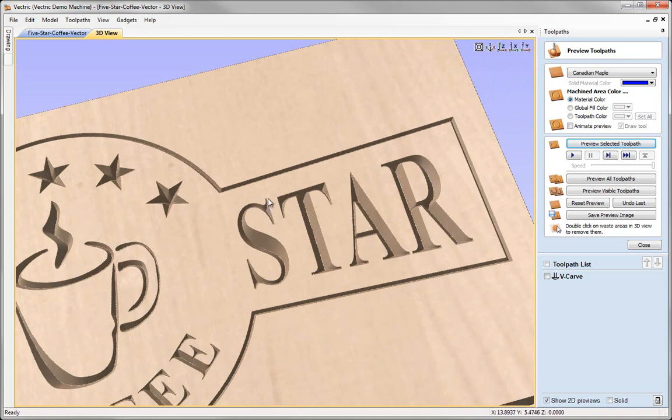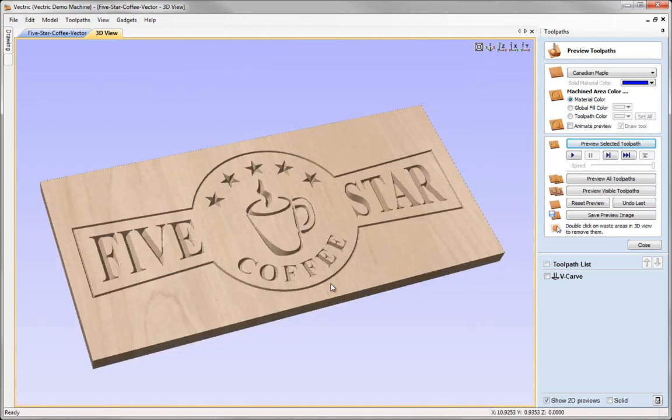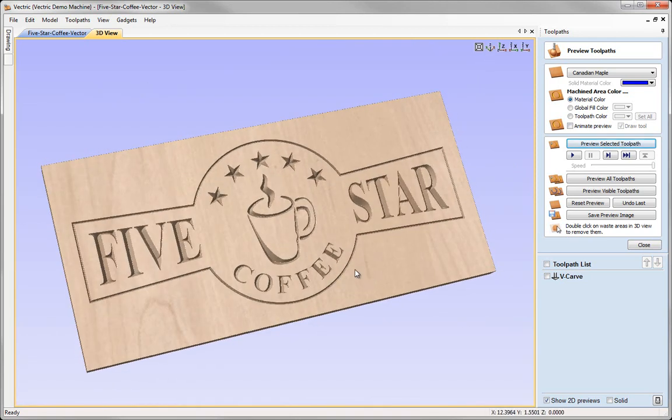So we can see in the angle as it comes around the top part of the S here is going to be quite shallow and coming up, lifting its corner to the top of the material in the serif. Then as it comes around and into the wider area, it's just going to get deeper and deeper as that tool can fit further down, effectively riding the rails of the vector. So I think for this job I probably want somewhere part way between.